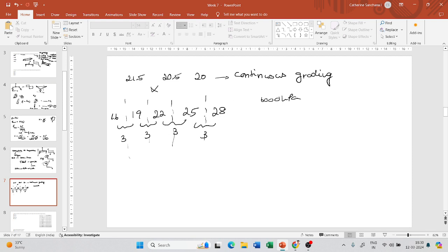If you give the exact value, it means that you are giving the continuous grading of bitumen, which you will call the pass fail temperature according to the dynamic shear rheometer. The results that you get from the dynamic shear rheometer give you the pass fail temperature, which is the continuous grading.